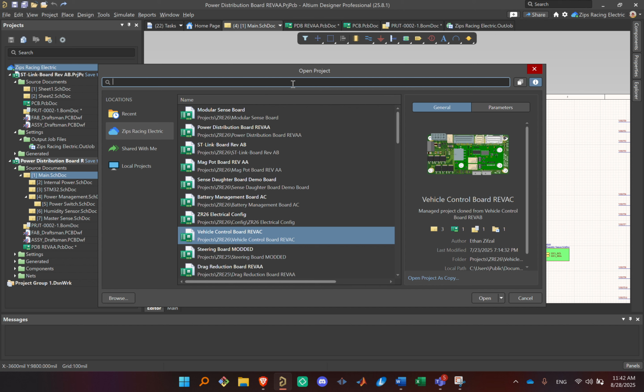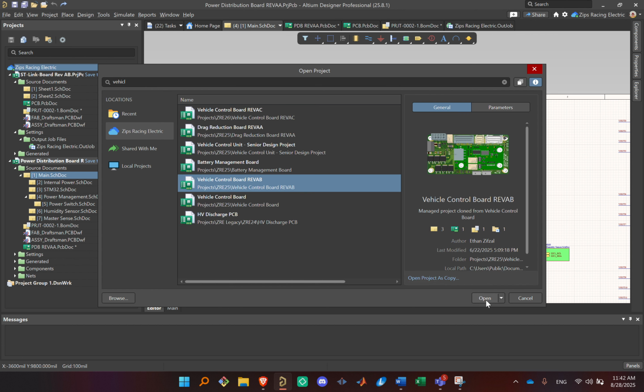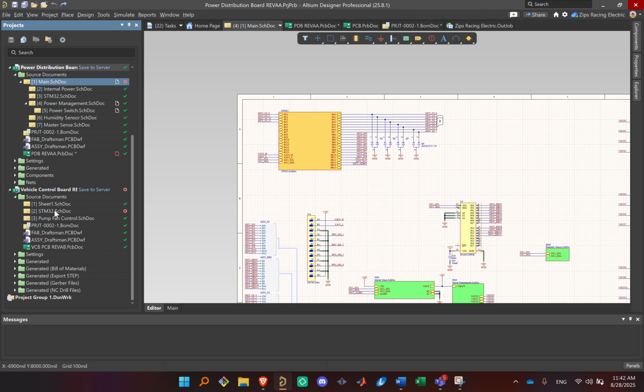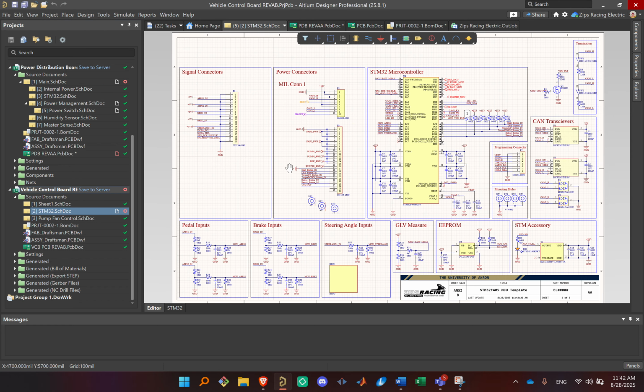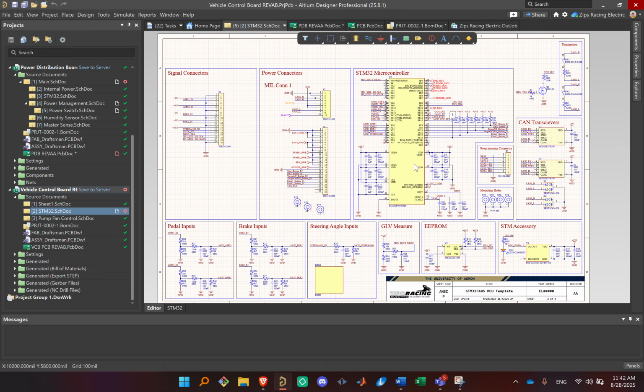So whenever you're designing a PCB, if you have 5 circuits that are the same thing, you only have to actually route it once, which is super convenient, and it'll save you a lot of time if you get comfortable with using that correctly. So this is what a board looks like if it's not designed hierarchically.